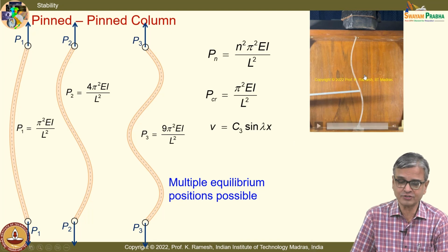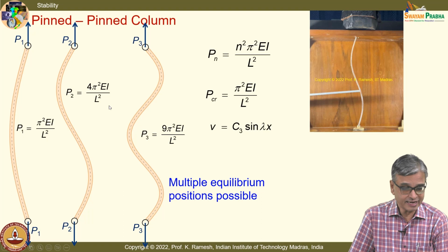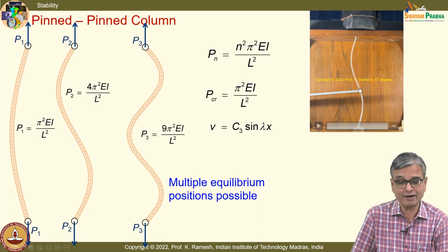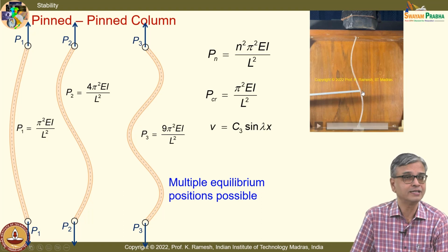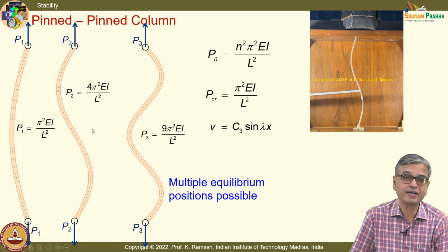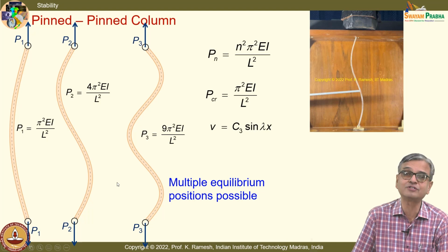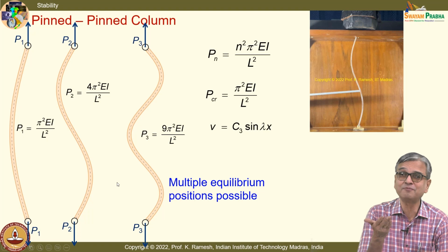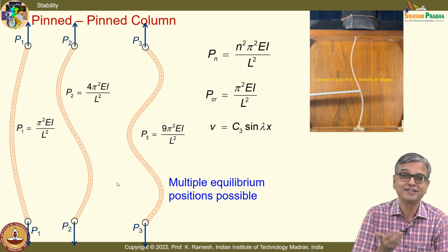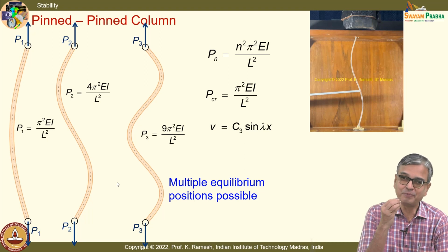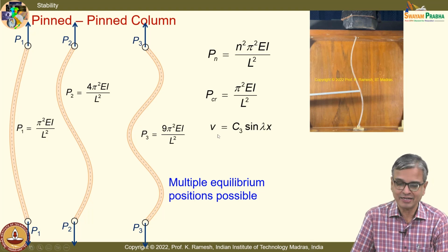And this shows experimentally I can get the mode 2, but I have to do something for the inflection point. I have to make that, only then I will be in a position to see that. Sometimes you will see I have such beautiful curves, you will wonder, can a column which looks so strong otherwise have a shape like this? In order to drive home that point, we have got this experiment done and it has come out beautifully.